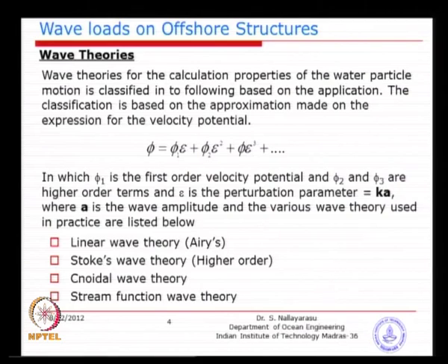Starting with linear wave theory, which could be a potential assumption that the amplitude is too small, that means the boundary condition is applied at the flat surface rather than the undulated wave surface. Basically similar to your applied mechanics, you might have studied in your basic degree the small amplitude beam bending theory.